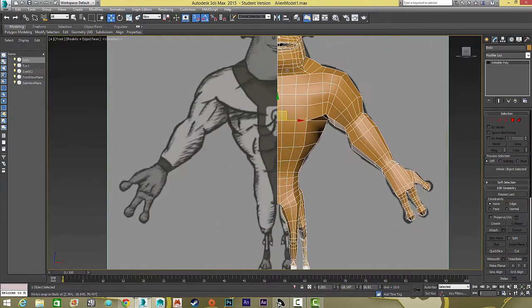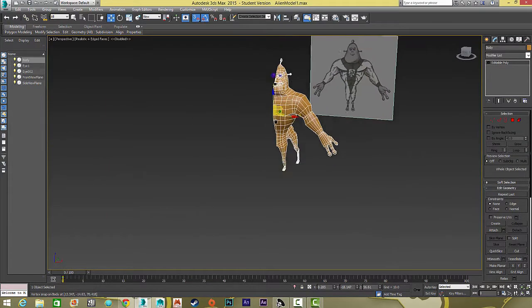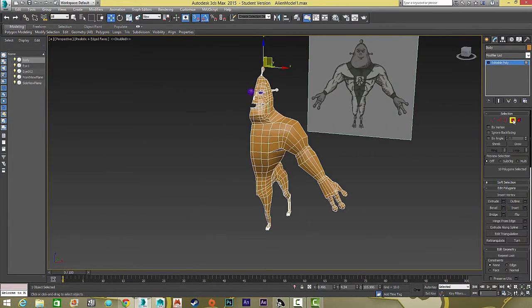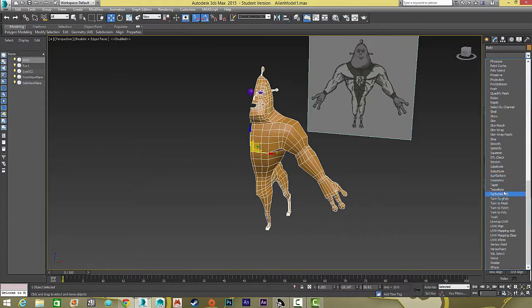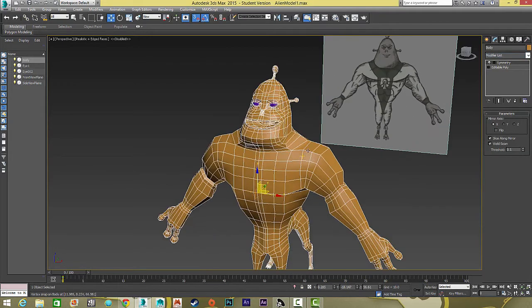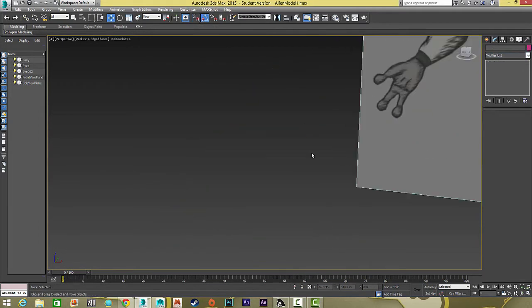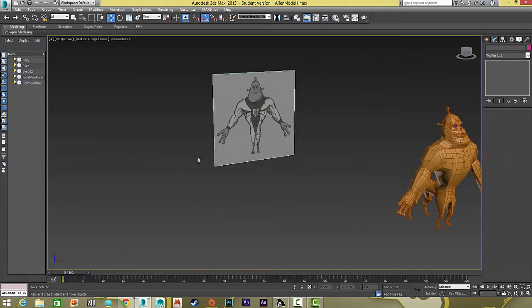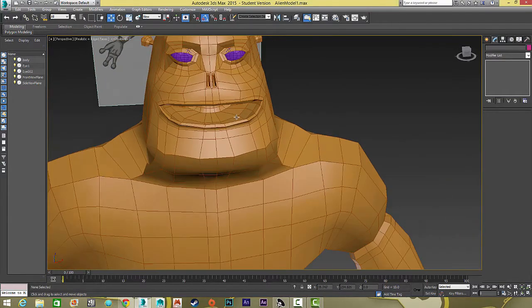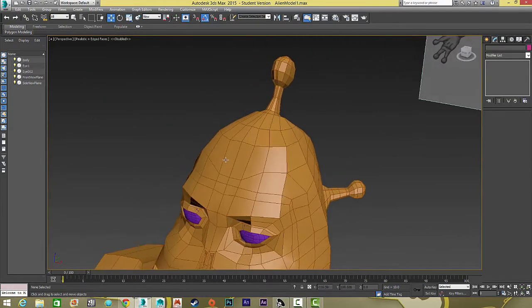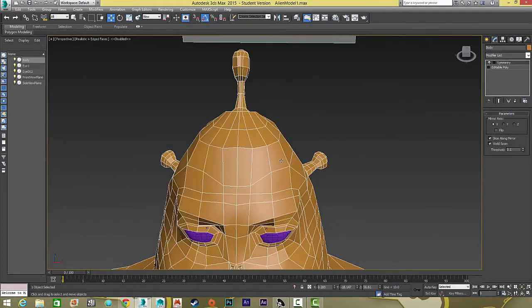Okay, so now always apply modifiers when you're in object mode. I want to apply one in sub-object mode, so the edit apply must be gray. And then let's roll back and find that symmetry modifier again. Now everything should be exactly lined up. Let's turn on my 3D snap for a second. There shouldn't be any overlap in areas anymore. It should fix everything because we've aligned everything correctly. And the bulb shape is set there correctly, so we're good to go.